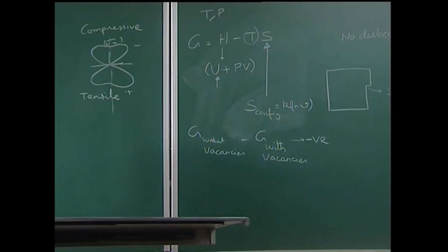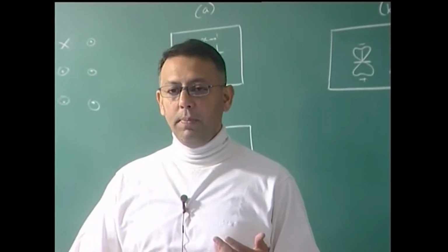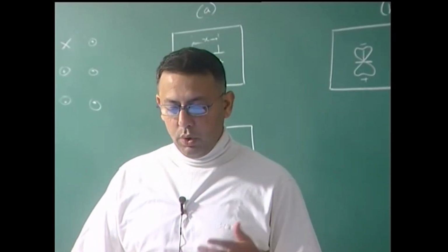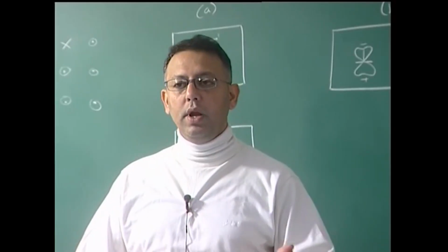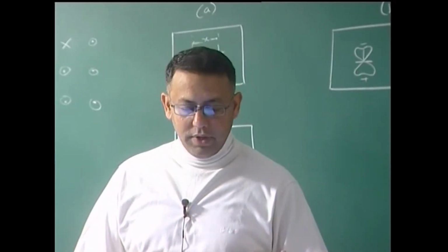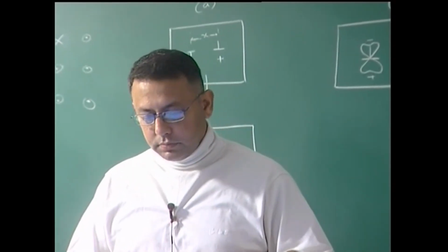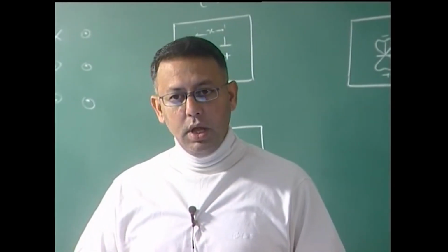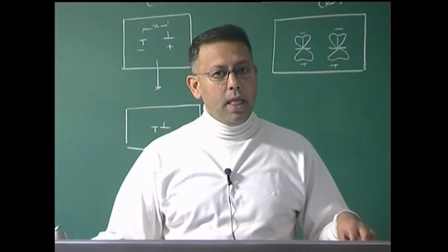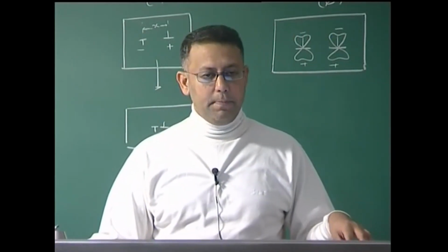On the other hand, suppose I had a system with dislocations or grain boundaries, and I heat such a system. There will be a tendency for dislocations and grain boundaries to leave the crystal, and in the process reduce the Gibbs free energy of the crystal. So, this is an important point to note: some defects like surface and thermal vibration are unavoidable in the crystal. Some defects like vacancy, in spite of being defects, are actually thermodynamically stable.